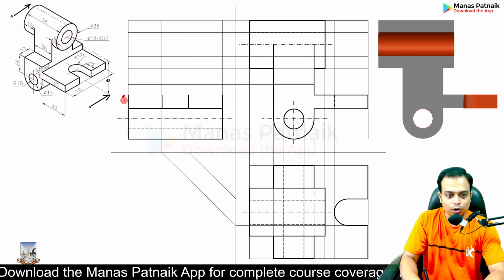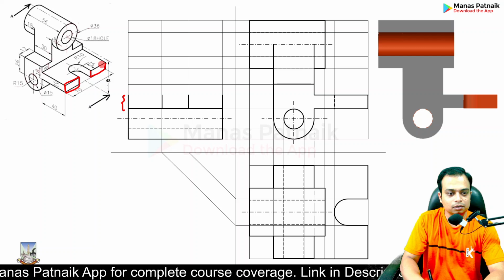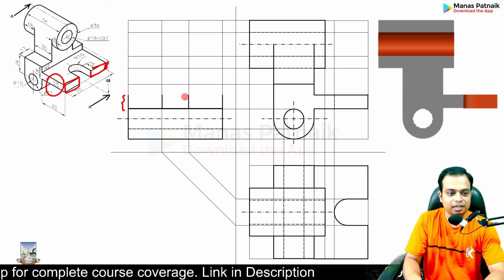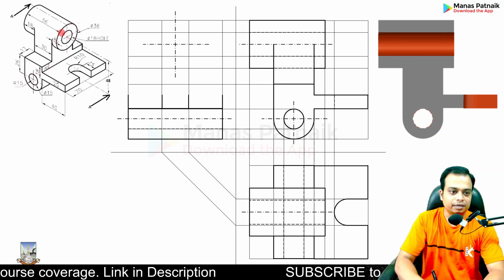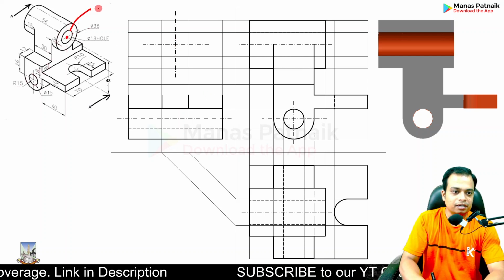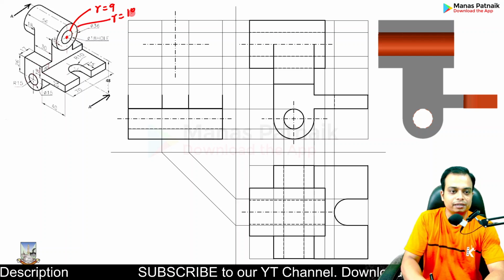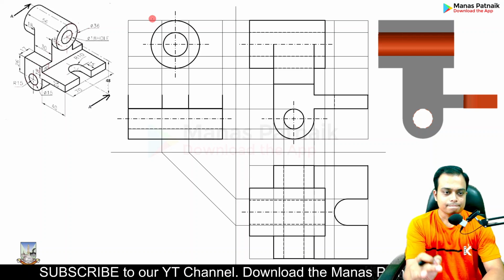And by the way, what about these lines, sir? What have we just done? We can make these boxes. These boxes are having a height of 10 millimeters. So 10 millimeter side. Give it some height. Done. And then locate the center. Through the center, sir, this is having a radius of 9. Sir, this is having a radius of 18. Make these concentric circles. Done.